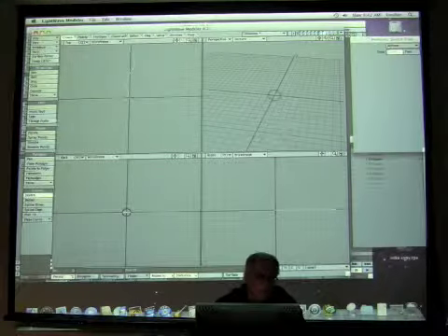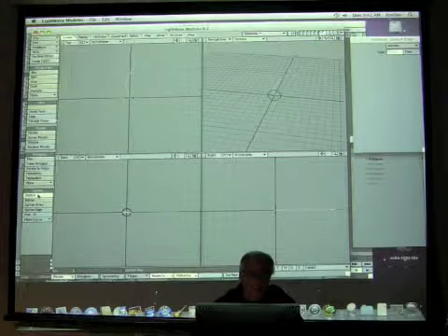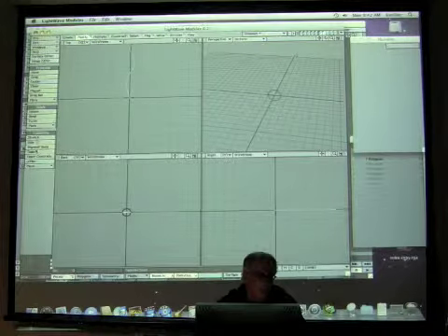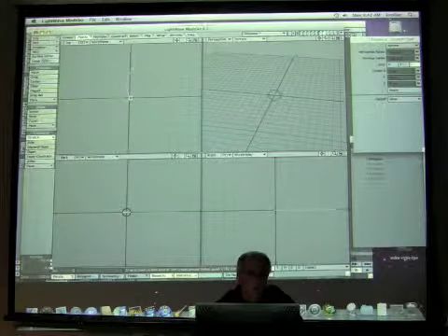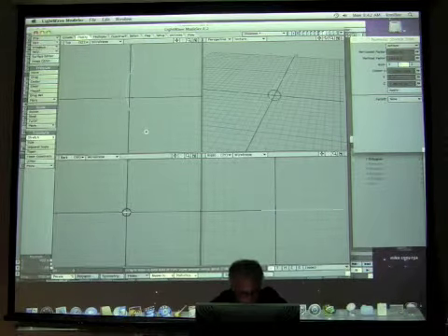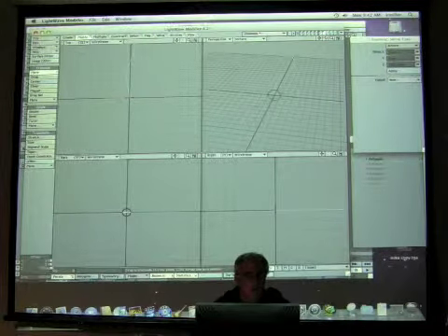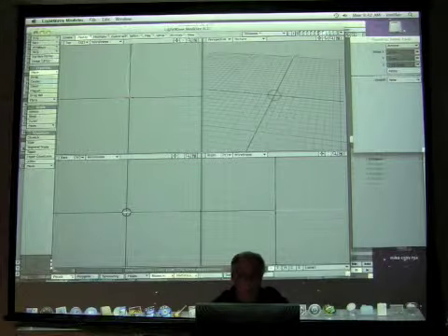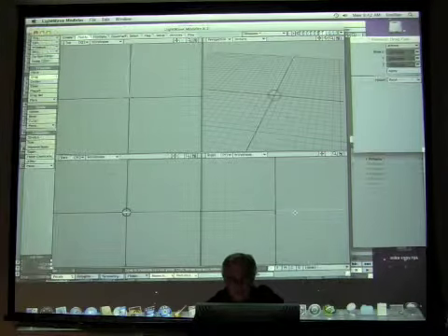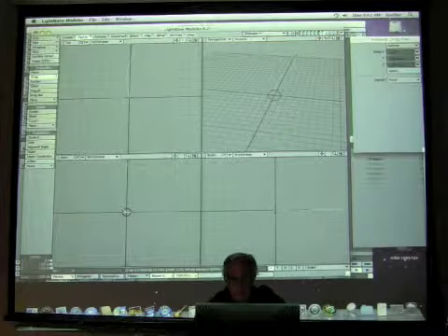So we'll go ahead here. I don't need sketch anymore, but instead I'm going to use modify, and I'm going to use stretch, and I'm going to stretch it from here, stretch it out a little bit. I'm going to hit T for move, and I'm going to move it so that this lines up like so. And then from the side view, I can use the drag tool, and maybe I can move one of these points up a little.